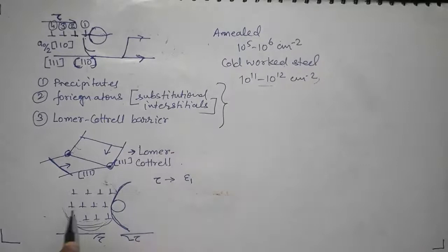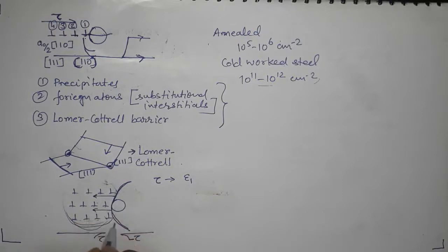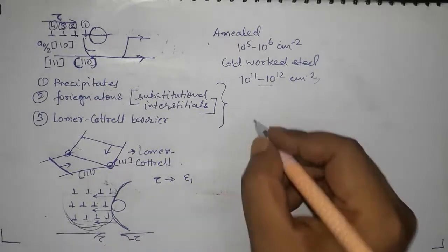So deforming a material can also activate the sources of dislocation. If you had fewer dislocations, you might have increased those dislocations, and all of them got piled up at this barrier. Now if you do the reverse loading, then you don't have to create that many dislocations. That is one factor. The second one is that these dislocations which were blocked are not blocked in this direction, so they can slip or glide in that direction very smoothly.